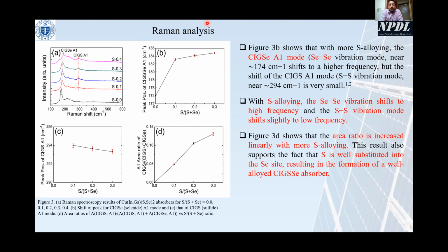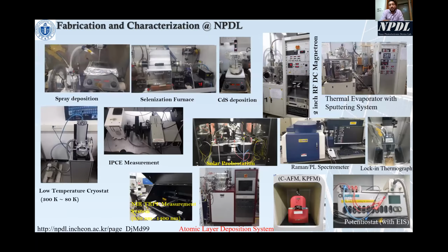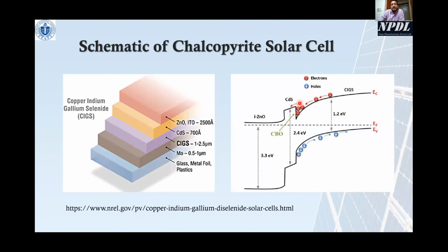But in our case, we believe that this is a direct band gap material. In the band gap aspect there is much controversy, but usually we believe it is direct, because in our schematic structure we didn't show any intermediate layer between the absorber and buffer; it's just a sandwich. So we considered that electrons can easily pass from the absorber to the buffer without any intermediate transition. That's why we consider it a direct band gap material.